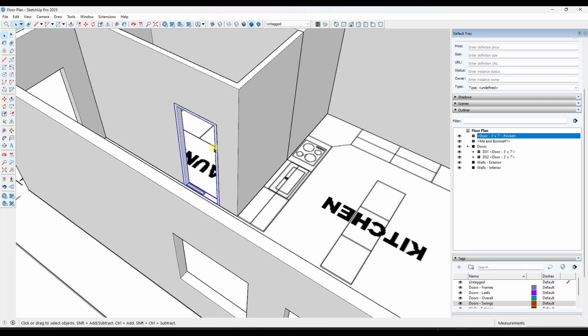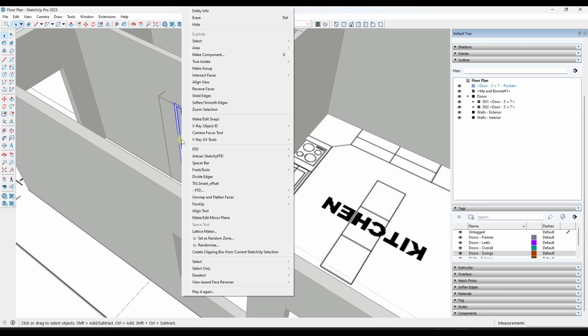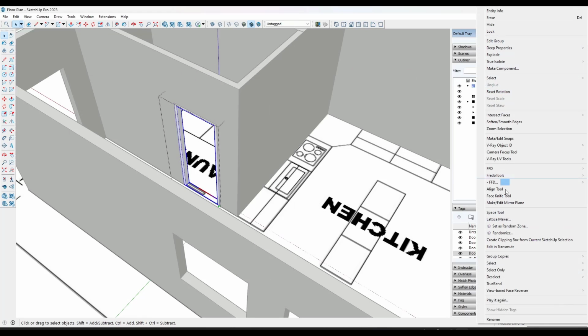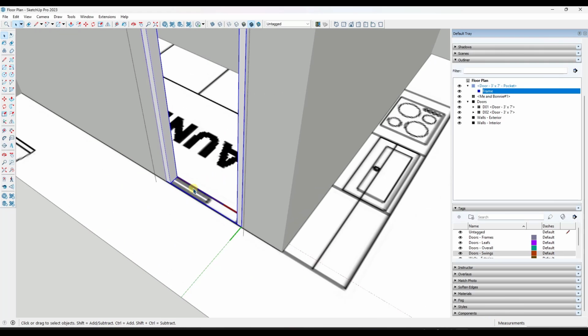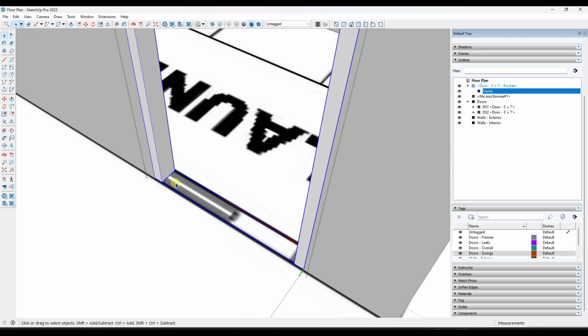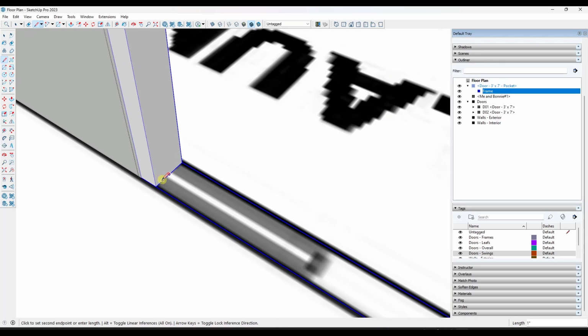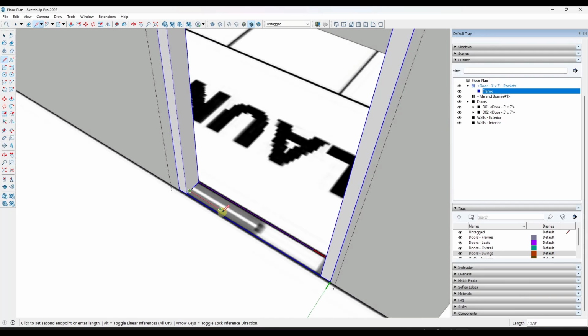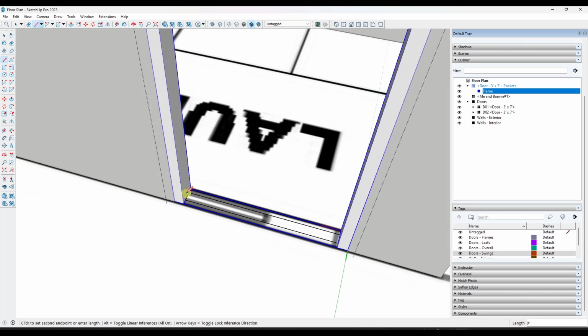And so within this pocket door, we're going to do the same thing, right? Except we're not really going to have a swing in a pocket door. So I'm going to take this frame and put it in a group. We'll call it frame. And then we'll model out our door leaf, which in this case is a little bit different, because we have to model it in the middle of the door. So I'm just going to draw a line that's 1 inch here, draw a line that's 2 inches here so that we're centered, and then we're just going to close this in.